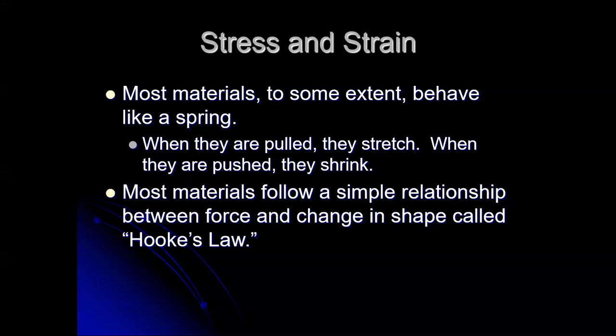It said that the force and the distance, the extension or the compression of the spring, were proportional. F equals kx, for example. We've got a similar kind of idea with most materials because the bonds between atoms and molecules act kind of spring-like. They're electromagnetic in nature, and that electromagnetism has a linear response as long as you don't push things too hard.